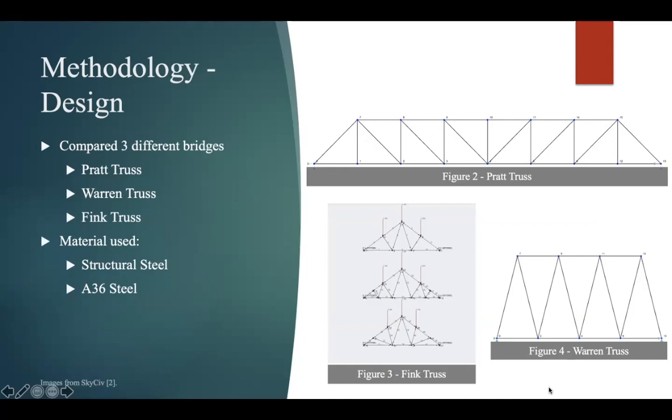The Warren truss bridge is made up of equilateral triangles, providing strength and stability while distributing applied forces. The Warren truss maximizes the use of material by ensuring the majority of members share the distributed load, thus reducing the overall cost of material and optimizing the use of labor. The Fink truss consists of web structures in a V shape. Due to its high strength-to-weight ratio, the Fink truss is primarily used as framework for railroad bridges and house roofs.